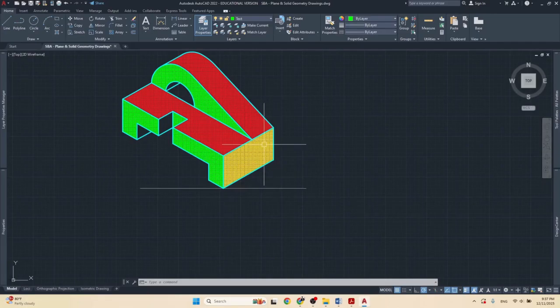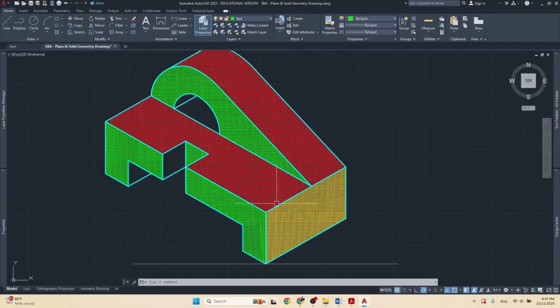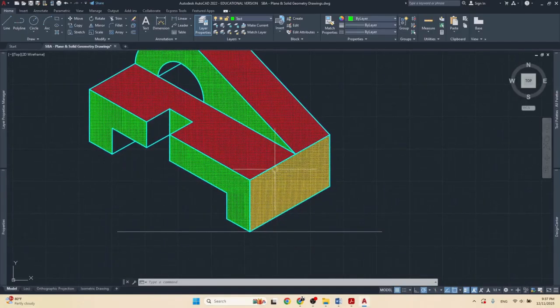But as you know, in technical drawing, we also have to represent things that we cannot see with the naked eye, by using hidden lines. So we would be able to depict this cutout. It goes in, let's say, 10 millimeters. You would see a hidden dash line come down here and come across to represent the cutout.